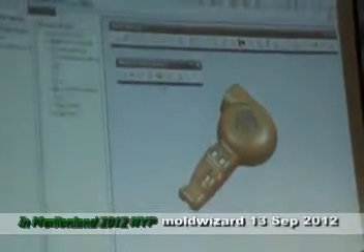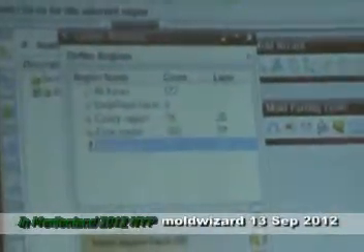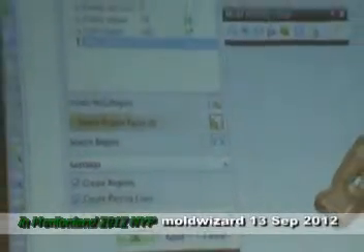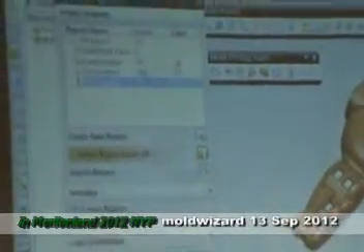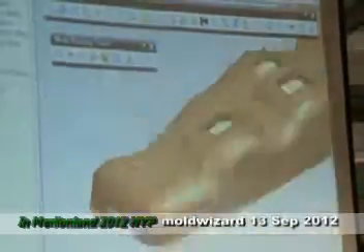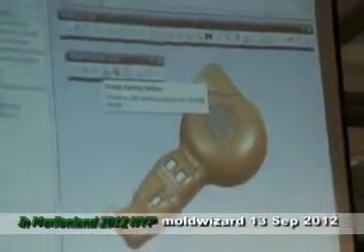Okay, the next one is define regions. So we need to create a region and then create a parting line. I think we just follow the same steps. So this one will be the core region, cavity region. Okay, good. Apply. Okay. Now the parting lines are created. I see this line is overlapping on the edge, just placed on the same edge, parting line. Okay, next one will be design a parting face.